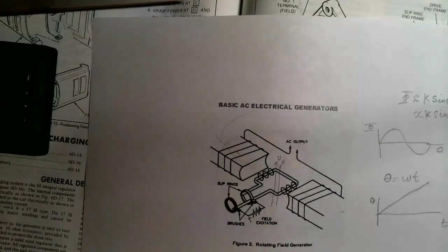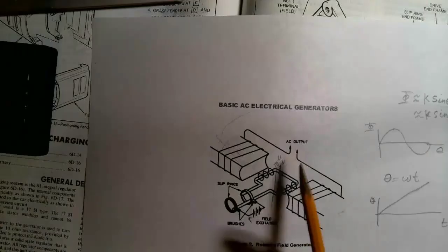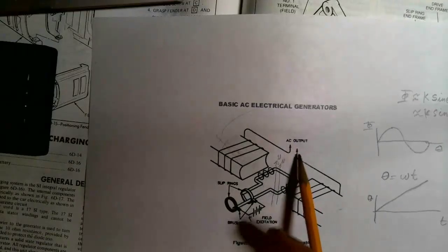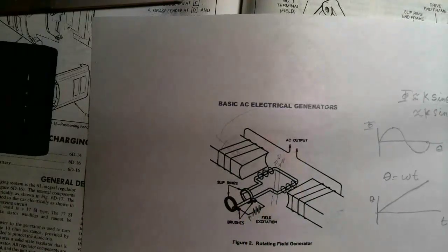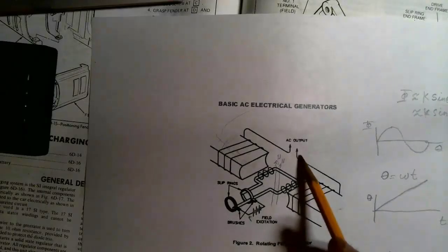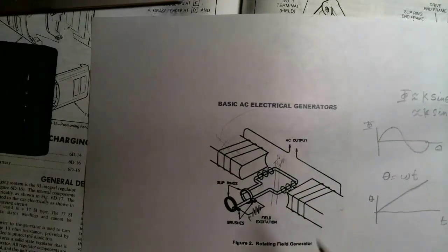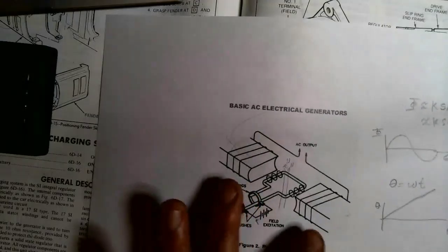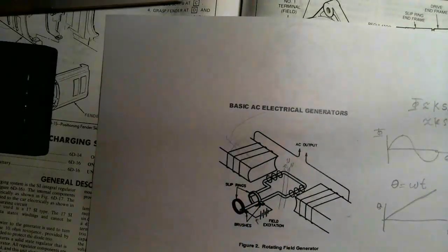So that is just a little quick tutorial on what the heck is an alternator, and they call it an alternator because it makes AC, and the AC output would appear across these two terminals. And by the way, these two coils are in series. So next, I need to talk about three-phase AC, because this would be just a single-phase AC right here. And if we wanted a single-phase generator that would make sinusoidal AC, you could have something like this, only this is a very simplified version of it.